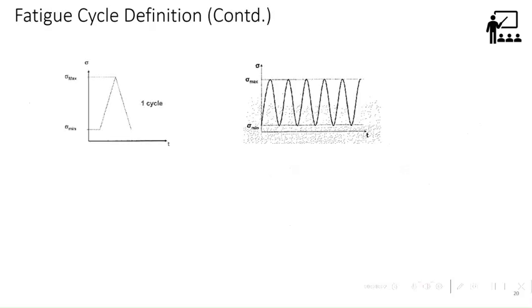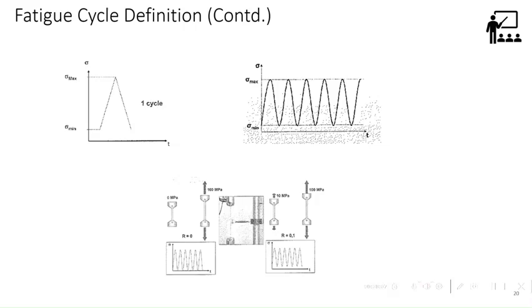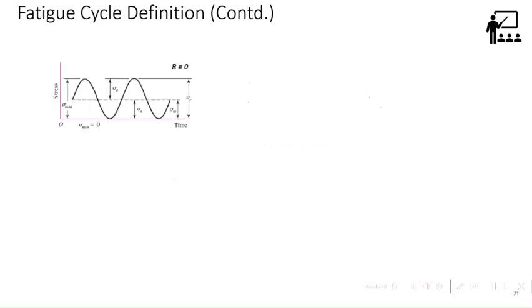And this is how you define stress ratio of 0 and stress ratio of 0.1. In testing, for R equal to 0, minimum stress is 0 and maximum stress is whatever the value is. But 0.1 means the minimum will be 10% of the maximum. And of course, the people who have worked on Airbus projects know R equal to 0.1. Why it has been done, I will share with you. Even your fatigue equivalent stress, why it has been generated at 0.1, why not any other stress?